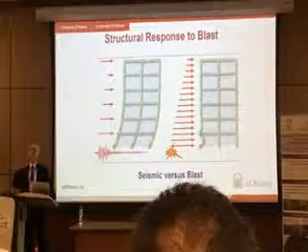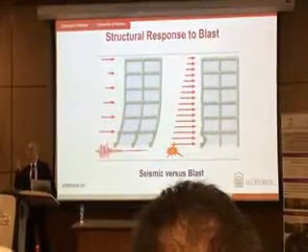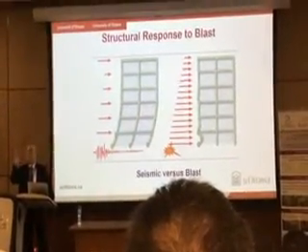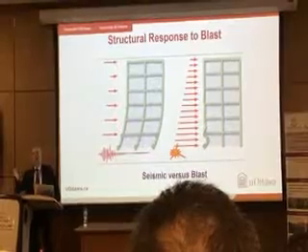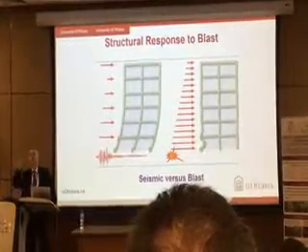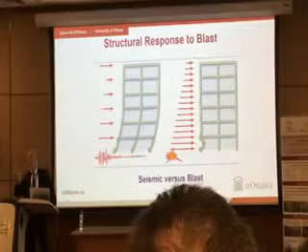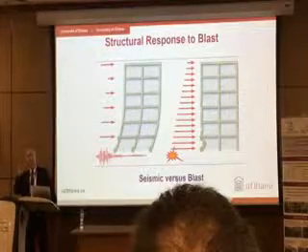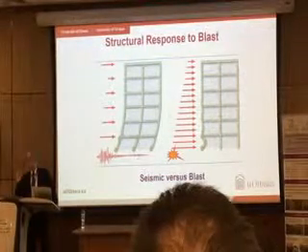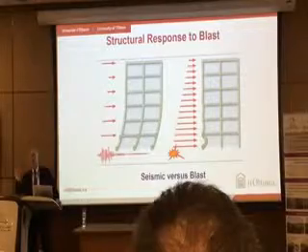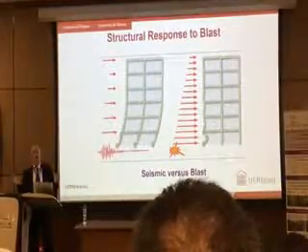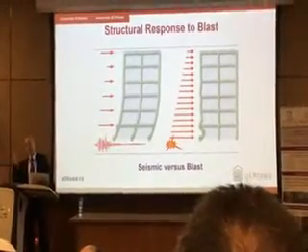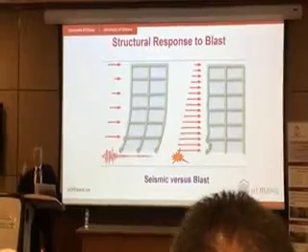If you have a high frequency earthquake, let's say the building is located on solid rock, then it will do this. This is the earthquake frequency, and if your building is reinforced concrete, 2 stories, shear walls, very rigid, your building also has this period. So if periods match, as you all know, a phenomenon called resonance occurs. So as the period of excitation, which means period of earthquake, approaches the period of the building, seismic forces increase. Theoretically, if they're equal, it goes to infinity, right? It never happens that way in real life, but periods are related.